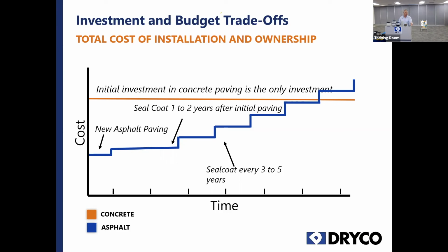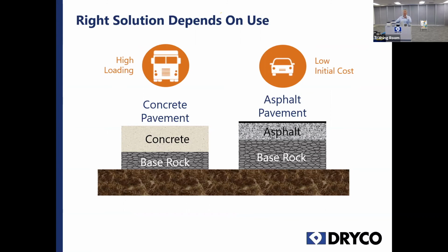So that's why your parking lots and your playgrounds and your large driveways are asphalt. It's because it's cheaper, right? And the problem with that is eventually it becomes more expensive. So if you look at the slide, you put it in, you wait a year or two, and if you're smart, you seal coat it, right? Because you want to protect it. And then you go a pretty good time, and then maybe you have a little repair, but you seal coat it again. And you keep seal coating and repairing, and eventually it ends up costing you more. Before at the end of its life, it ends up costing you more than concrete would have if you had used that as your initial investment. So concrete's cheaper in the long run if you can afford the right use.